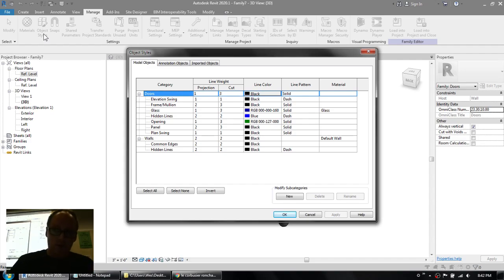So what we're going to do now is go through the process of creating a window where we're going to have two frames. One that's an extrusion, that's a very basic geometry. And one that is a sweep that's at a different level of detail. So over the next few pages here, if you folks want to, bottom of page 8, you're going to use that splayed opening family that we talked about. And I'll let you folks go through the exercise there. And in about 10 minutes, I will jump in with you.